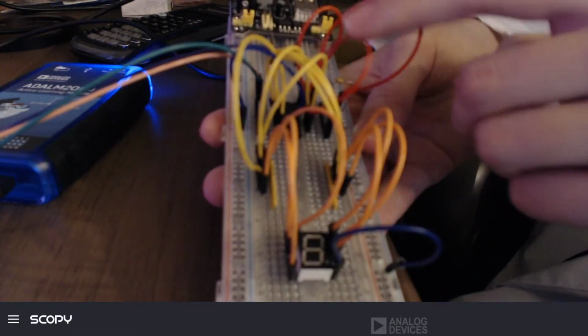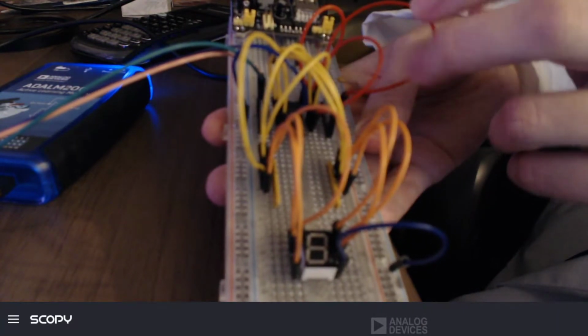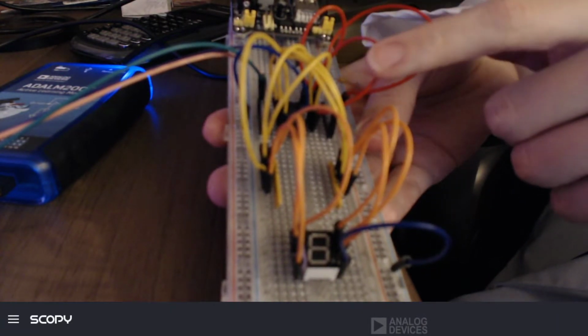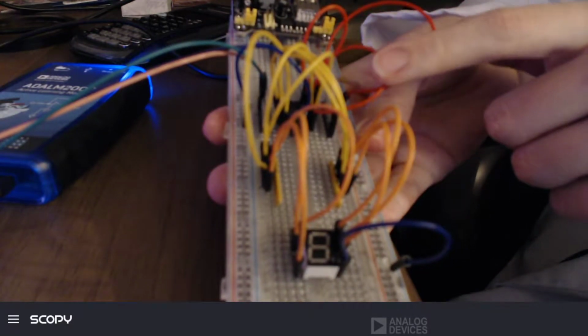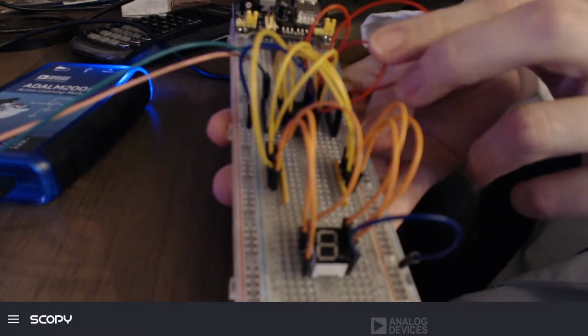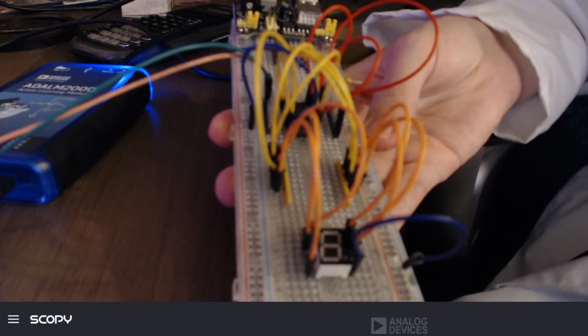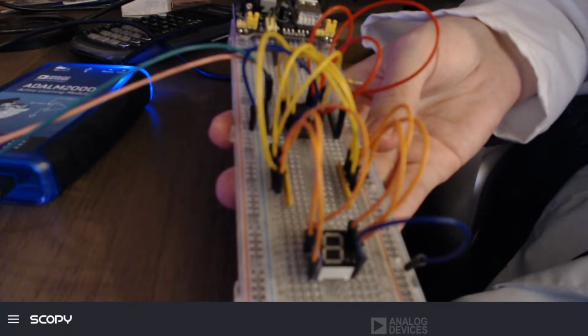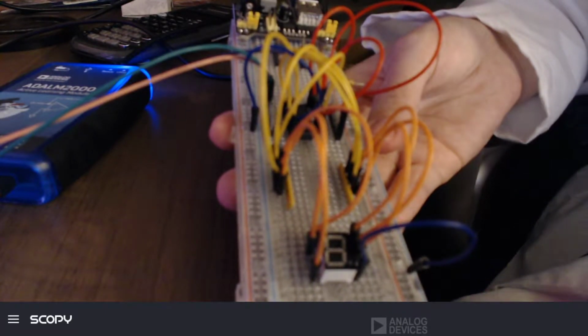Simply put, we have voltage, 3.3 volts from our power supply going into our VCC, as well as a reset pin. The reset pin could be given a button, but for now, for this lab, we'll simply send it the information to tell it that it won't reset. So if you send logical 1 to the pin, it won't reset. If it gets a 0, it'll reset it.